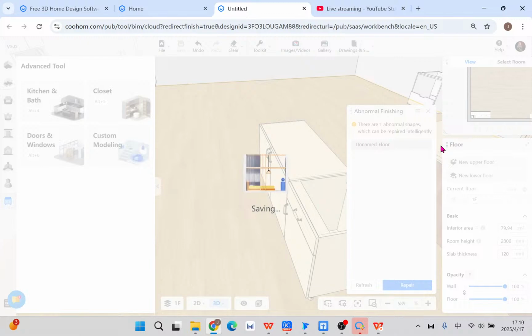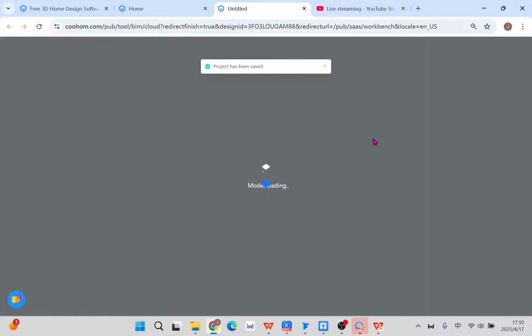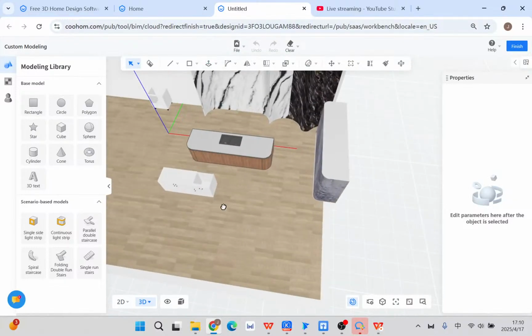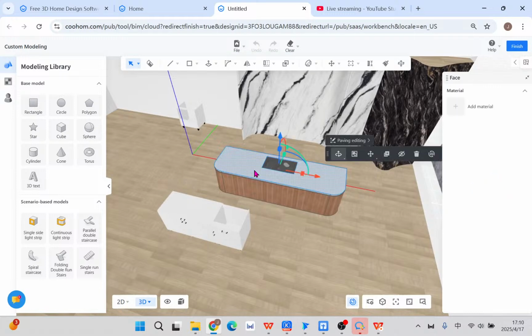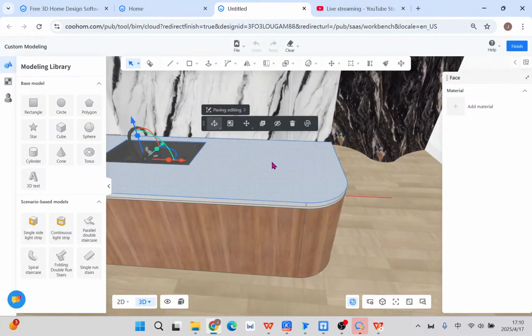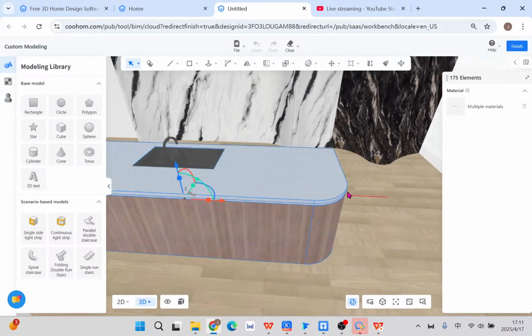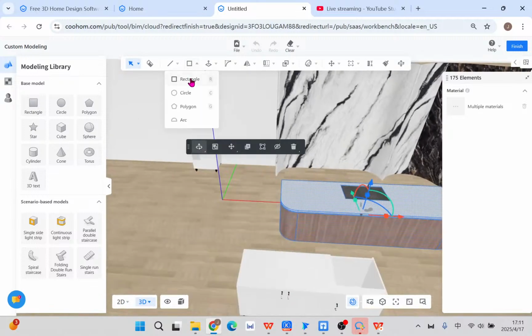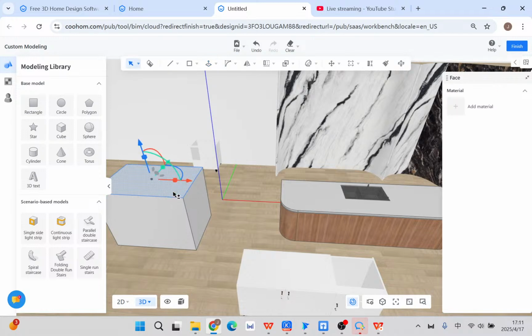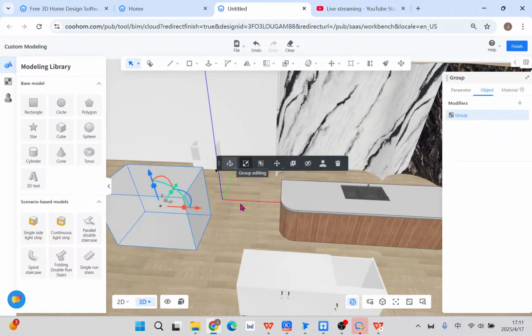Sometimes, if you want, my suggestion is not to use the move. I know some of you really prefer to use the move, but in my opinion, I suggest that if you want to duplicate something, or put some elements into a proper position, use the copy.